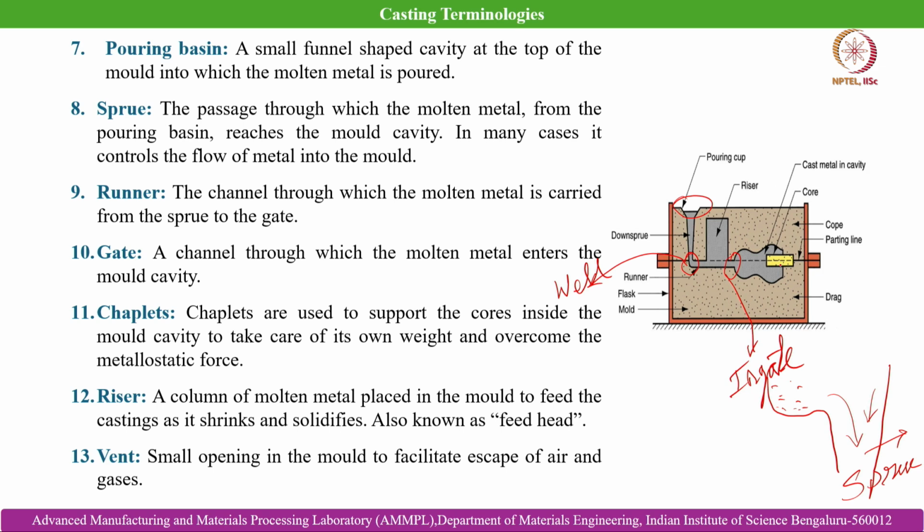And then the riser. The riser is basically kept like a reservoir, which is necessary to feed the solidification shrinkage the solidifying component is undergoing. As I already explained, the solidification shrinkage happens due to the density difference between the liquid and the solid of the same material, and the riser is the essential part of the mold cavity to feed that solidification shrinkage. So, it is also called a feed head or feeder head.